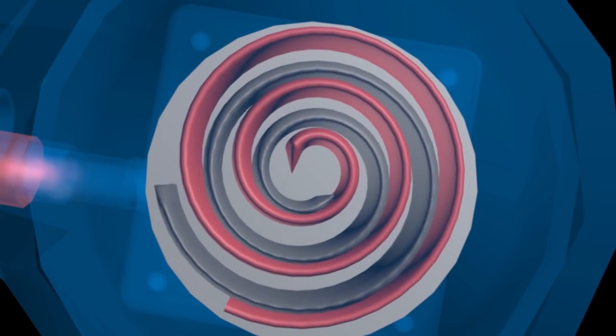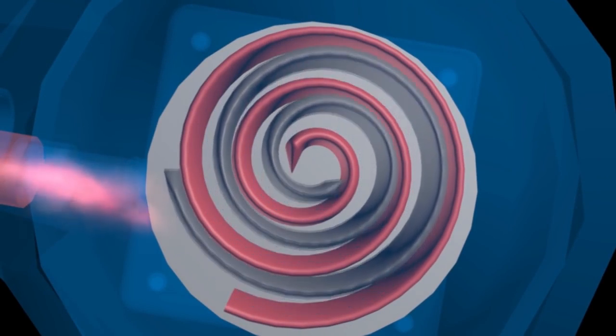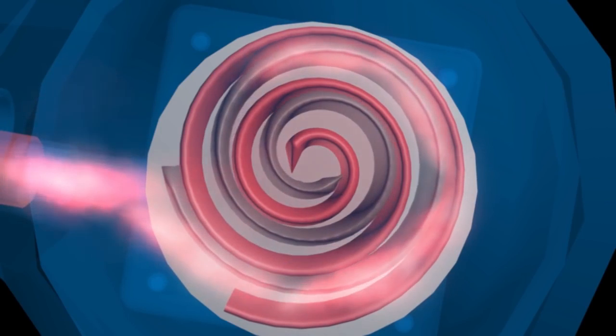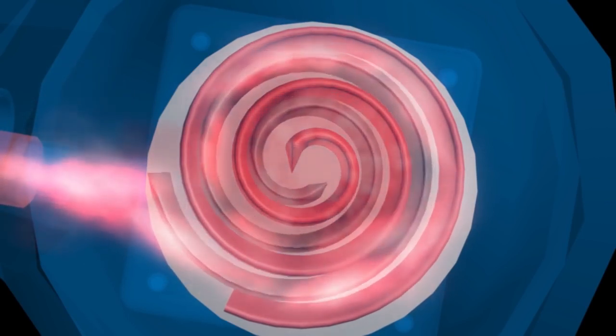The type of compressor used is the scroll hermetic type. Scroll compressor works as follows: gas at low pressure and temperature enters the suction line and goes into the compressor. The low pressure and temperature gas is pressurized by the scroll compressor to high pressure and temperature gas. The high pressure and temperature gas is then passed through the discharge line and goes into the condenser.